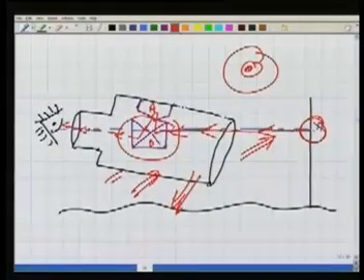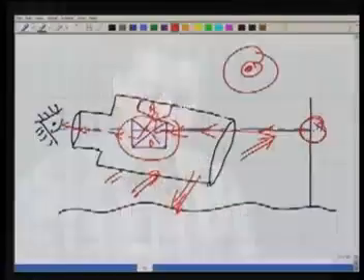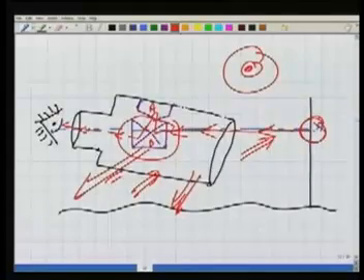So my telescope is nearly leveled. The line of sight is not horizontal yet. Nearly leveled. Now the rest of the job is being done by the assembly B and A. They will ensure that even if my telescope is nearly leveled, or not perfectly horizontal, the line of sight for me is now horizontal. We will see a demo on this auto level now.